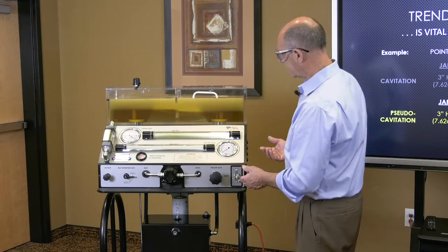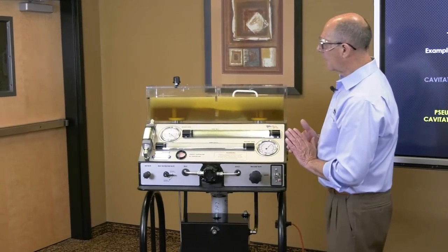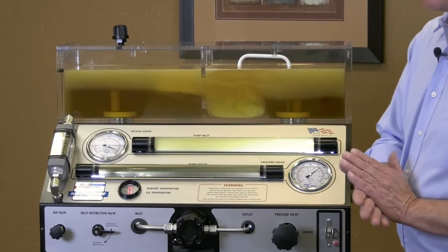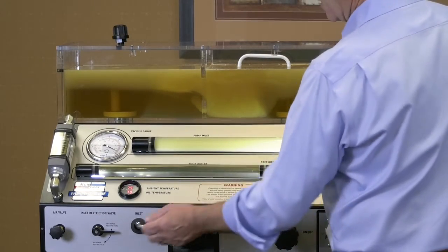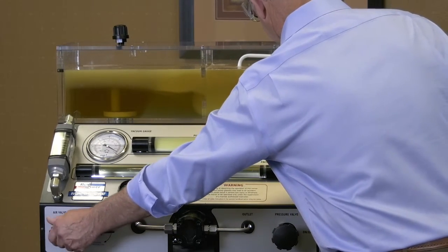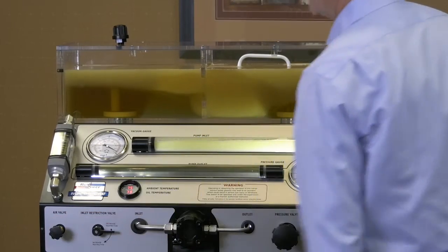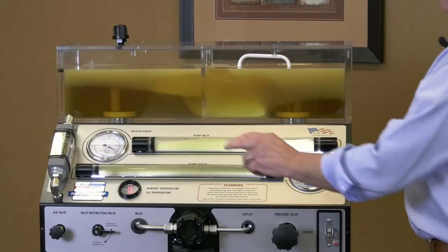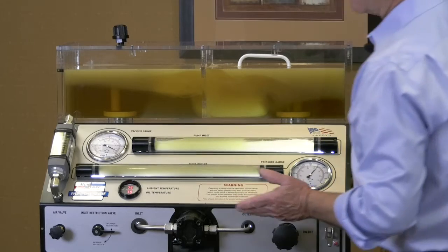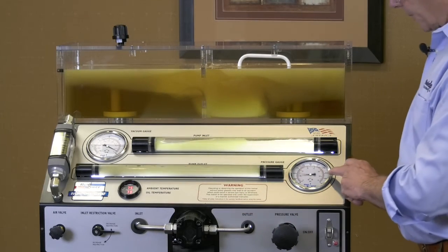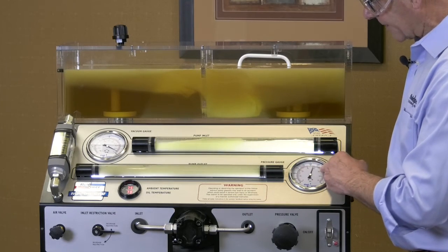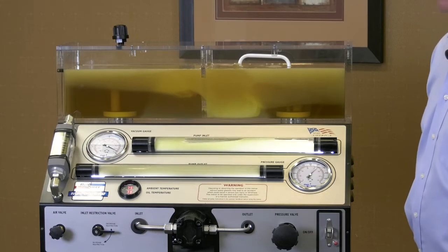So, once again, let me start it up. My pump flow, as we learned, was 1.8 GPM, and now that I'm allowing air to go into my pump, my flow is compromised. My flow is erratic, going from about 1.7 GPM down to about 1.2. My pressure is erratic, fluctuating between 650 psi and 100 psi.